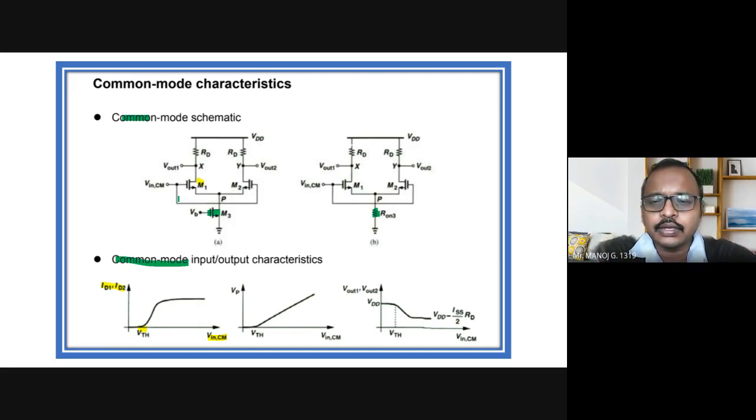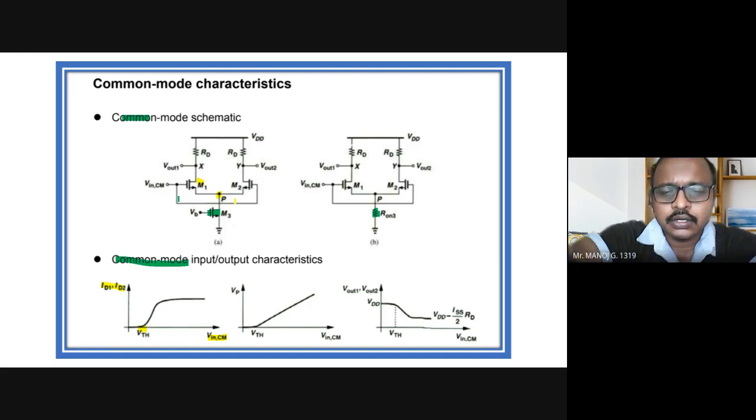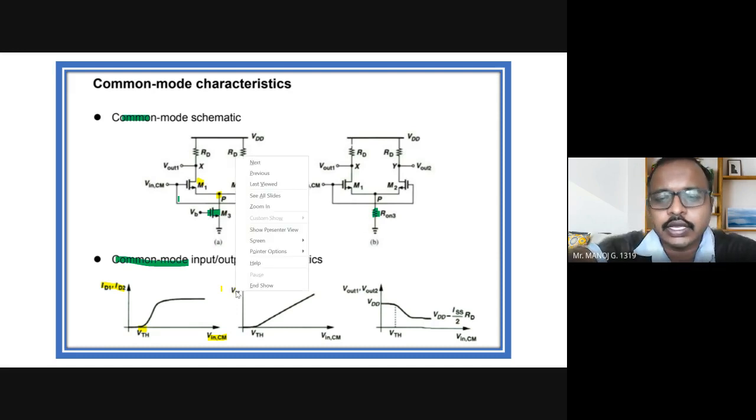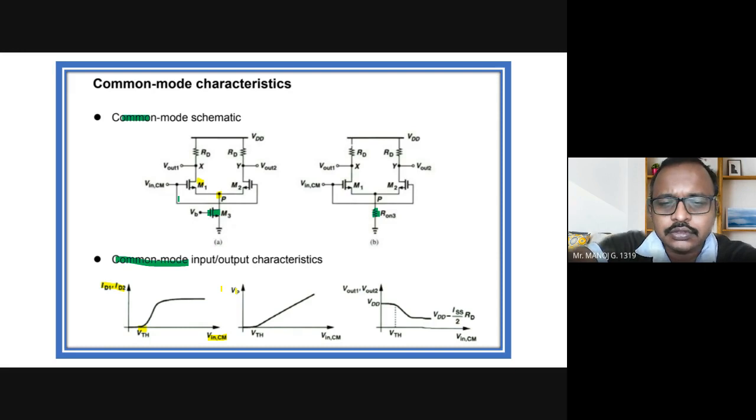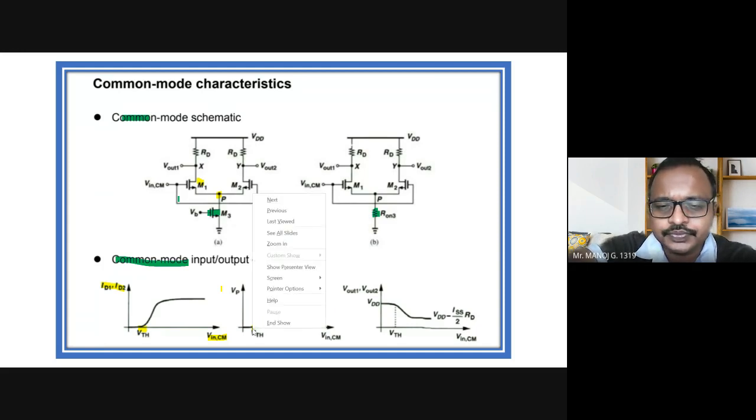What is VP? It is nothing but this point. This VP point is very crucial because this is the point where the symmetry is split up. That whole point of voltage setting, that VP point, is very significant in analyzing the characteristics. So how VP varies with respect to Vin is something like this: a linear steep increase in the voltage after the threshold voltage.